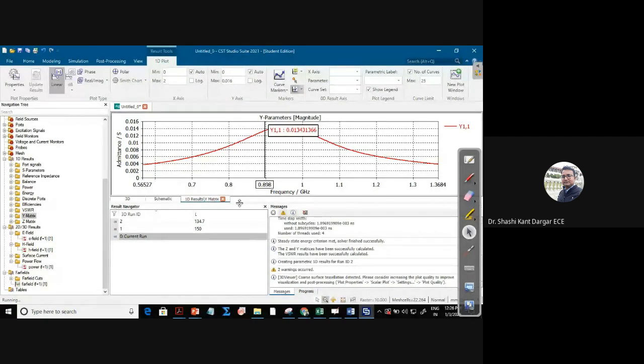You can take the screenshot of pattern. I want the E field, H field, magnetic field, static pictures, screenshot from you, defined at 1.1 gigahertz. Design a simple dipole. Also check the efficiency of the project. Efficiency of power, energy, everything you can see in the 1D results here because we defined only one pole. With this, I would like to end this lab.